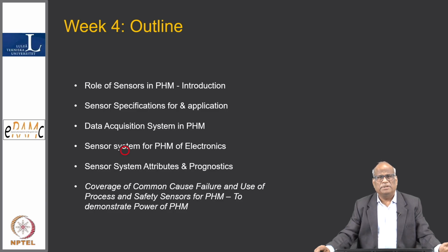Let us say if I have to maintain a ground benign environment in a place, a control room or instrumentation room, if I have to maintain the GB condition, ground benign condition, that means I have to have 22 degrees centigrade temperature and 50-55% humidity. So we have to maintain that, otherwise the electronic system might not perform the way it was expected.